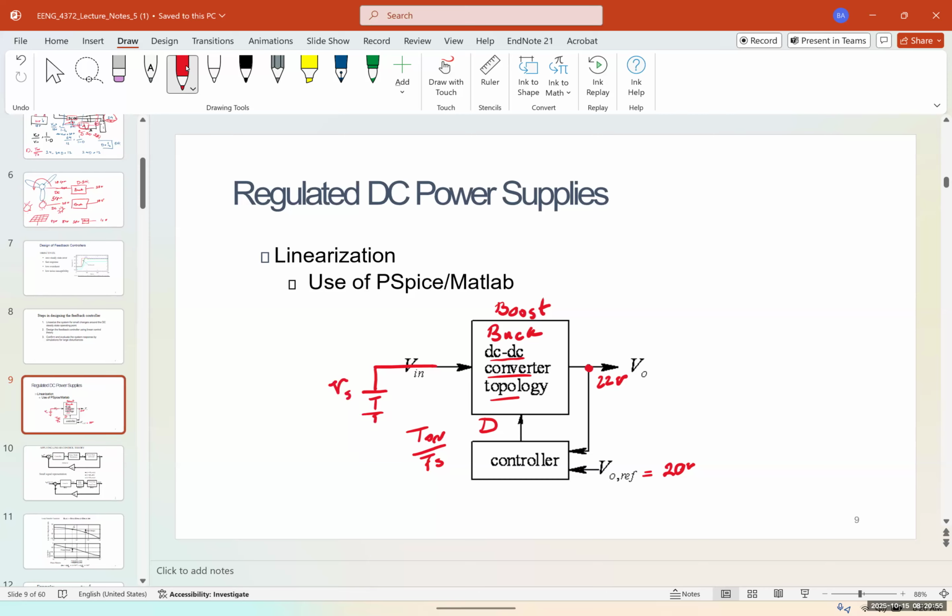Now T(s) in the system is going to be K over 1 plus s over omega 0, and if we want to write it in the logarithm equation and find the magnitude of T, it's going to be 20 log of T(j omega), which is 20 log of K over the square root of 1 plus omega over omega 0 squared. So just keep in mind these two equations.